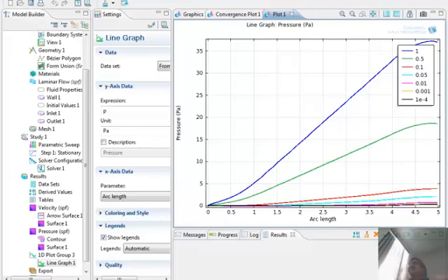And the same question, how do I know whether the results that I'm getting are right? You need to benchmark that. You need to take a known result and compare against it. For example, for the geometry that you are doing, by setting the parameter you can make it into a flat plate. Before you start trusting the results for the converging channel, do the one for the flat plate, where you have the analytical result, and compare and make sure that it agrees well. Then you know that your code is working in the limit, and then you can push it away from the limit into the domain where you want to really explore and nothing is known.